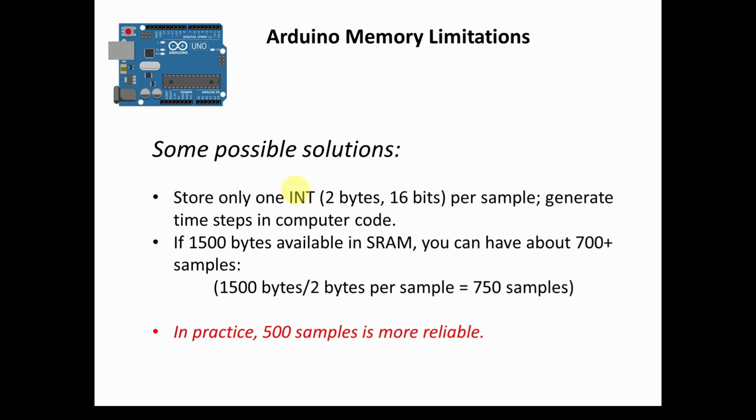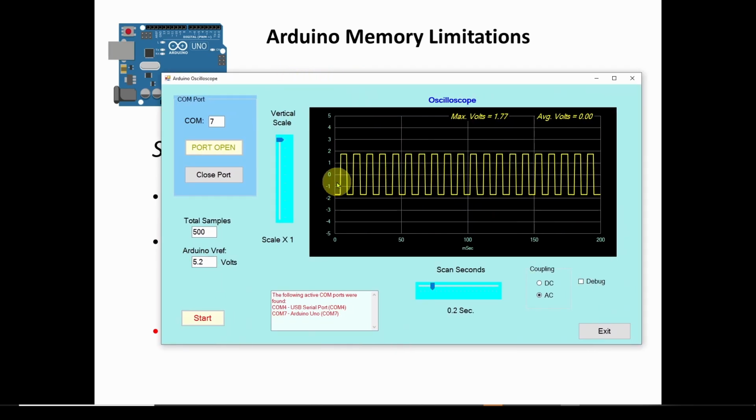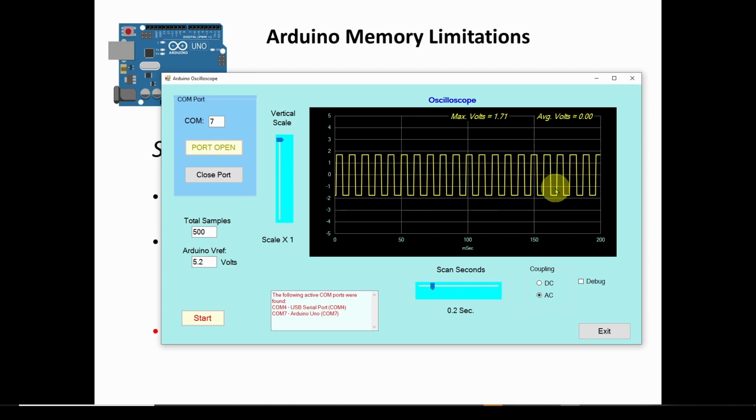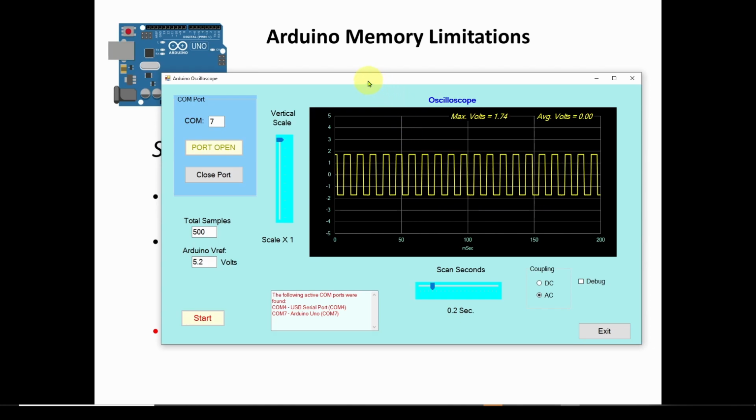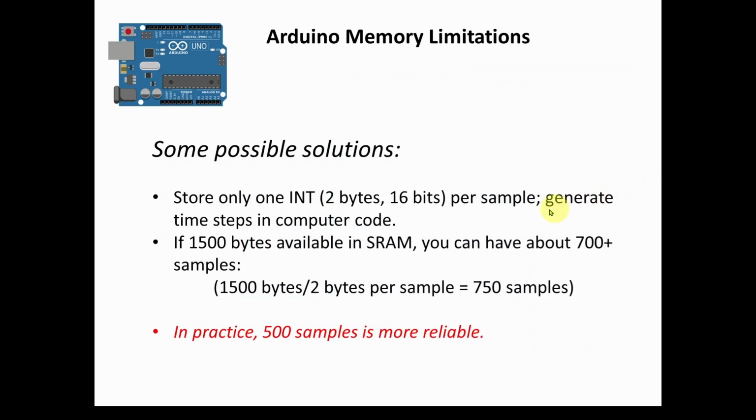So you take the time between one microsecond reading and the other, and that tells you how many microseconds between samples, for example. But can't we just generate that in our computer code? Can't we say, okay, we're going to assume that this starts at time 0 and we know what the sample rate's going to be, so why not just generate our own timing instead of using those values from the Arduino.